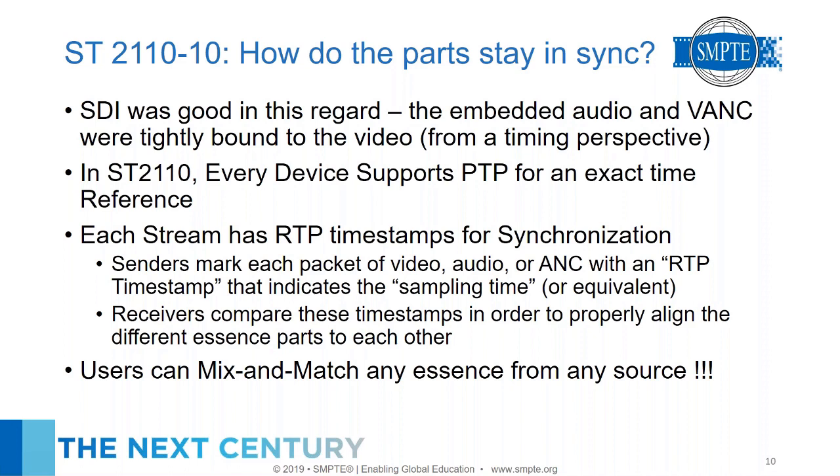Thank you. John, this is a topic that you and I have discussed before, and it has to do with RTP timestamps. You say quite clearly, probably the most clearly I've ever seen, that the RTP timestamp should represent the sampling time, which is great, and then we can use that to realign. But I wonder if you could comment about what happens in a downstream device that is, say, receiving a 2110 signal, processing it, and then re-injecting into the network. Is there a standardized or recommended practice for that device's handling of the timestamp?